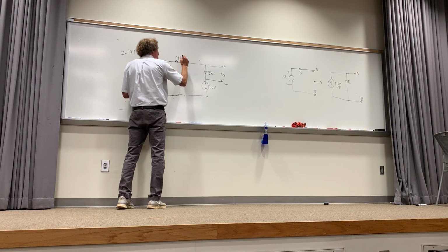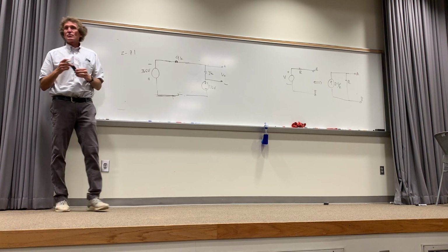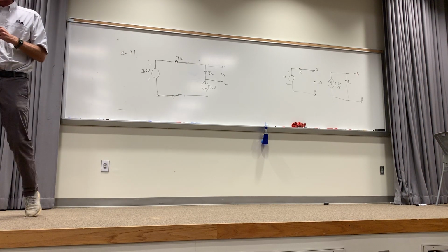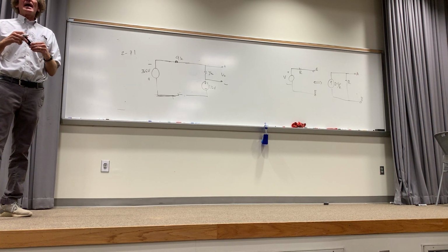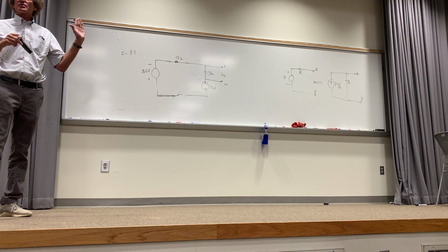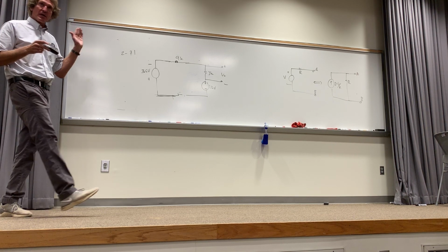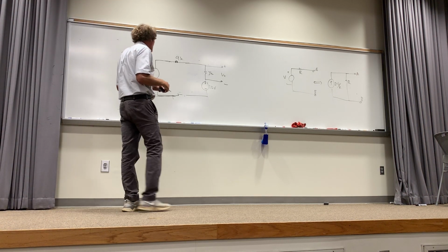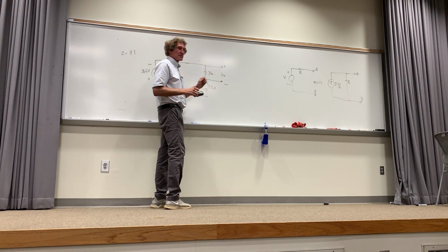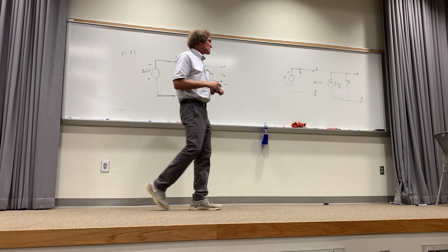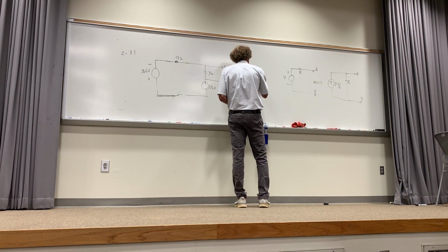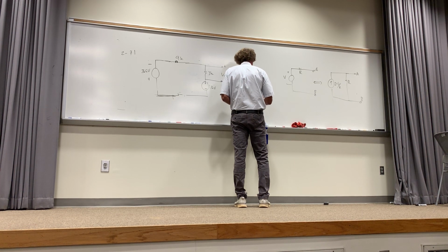That's 9K. You agree with me? Now here's one thing I want to underscore. The last thing you do is put the resistor or element that you want the voltage or current through in. You never source transform it. So I'm not going to source transform this. Got me? But I want you to notice something that I'm going to say explicitly.